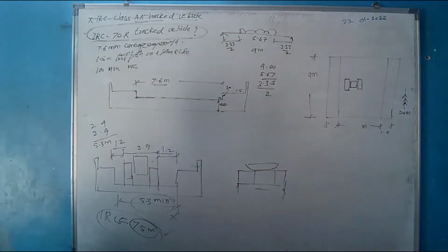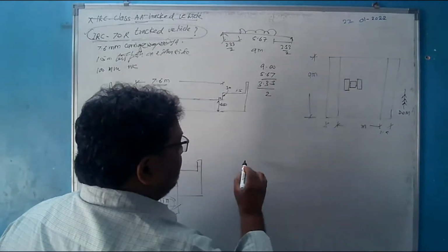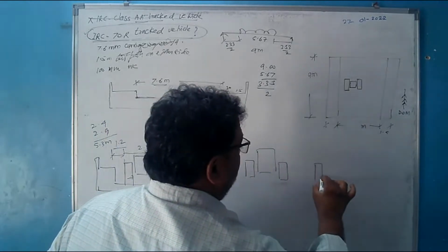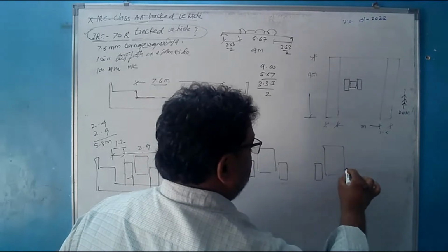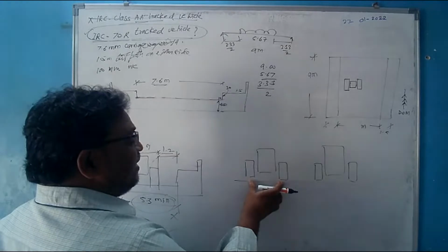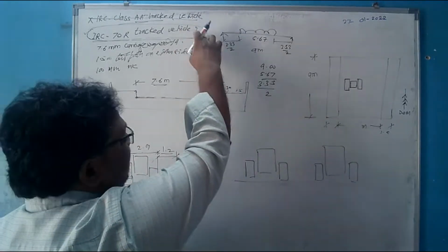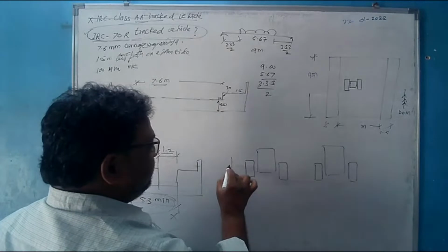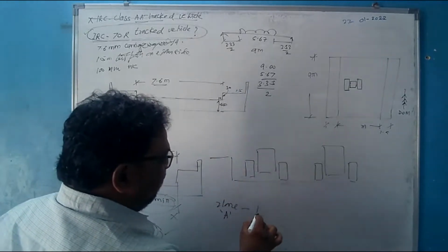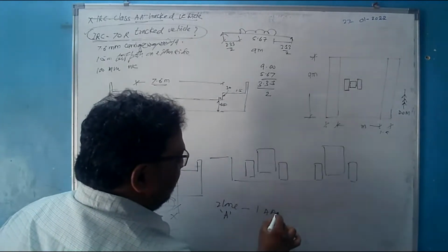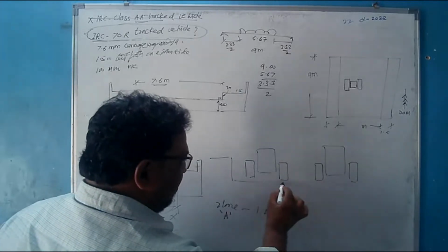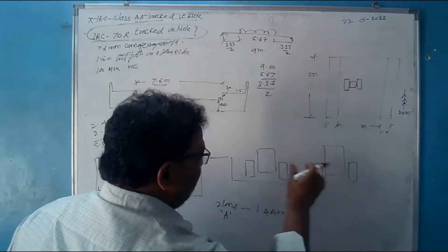Again, because of any reason, say there are 2 vehicles which are passing or crossing. If this were a 4 lane bridge, then for every 2 lanes we would consider one IRC 70R or Class AA vehicle, so we consider 2 vehicles. For 2 lanes of A, it is 1 vehicle of AA or 1 vehicle of 70R. If this is a total of 4 lanes, suppose, then one vehicle is for these 2 lanes and one vehicle for the other 2 lanes.